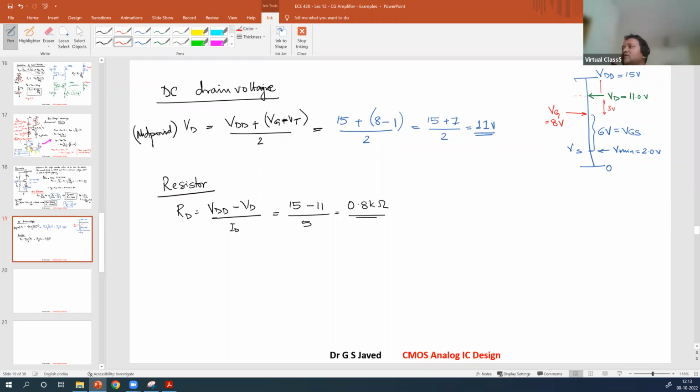On this side, you have a 4 volt swing here. So your input can swing at this range, output. Okay. So this is VGS minus VT as a rate. So VG minus VT, 3 volt is what you will get swing here. So hope you understood.